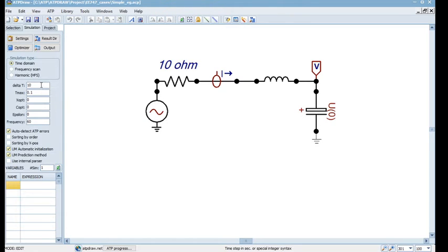Just to show you, I'm choosing this randomly, but you should not do that. So let me just go with that. I'll specify it as 10e minus 6, so it's 10 microsecond kind of order. Or if you want, let me just make it 100 micro, no worries. Yeah, 100 microseconds, and you want the simulation to run to, let's say, 0.1 seconds, and the rest of the parameters, let's not worry. This frequency also won't matter unless you are doing some other kind of study. So in time domain it won't matter at all.